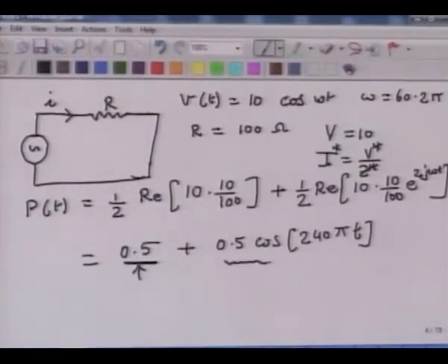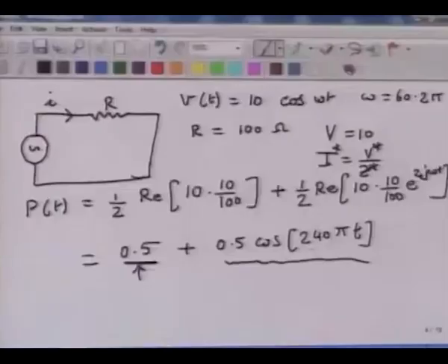this power is a cyclic thing. So in part of the cycle, energy gets stored by the system, and in another part of the cycle, energy gets dumped back into the system. It does not get dissipated. So it stores and releases the energy, going back and forth. The other thing you will note is that the frequency of this is twice the frequency of voltage or current, or in the acoustic domain, whatever the source signal's frequency is, it will be twice that.